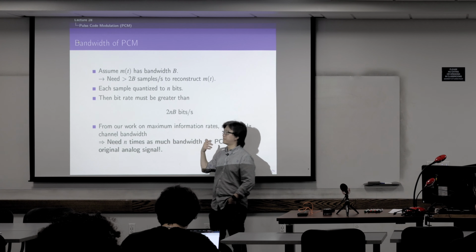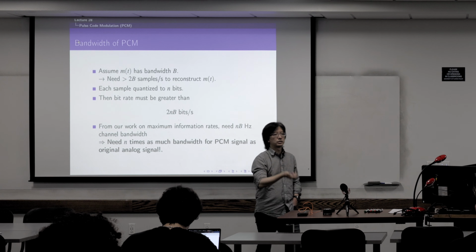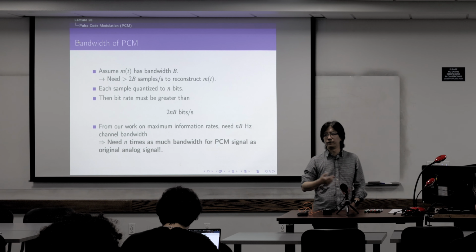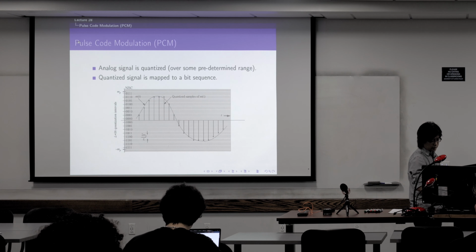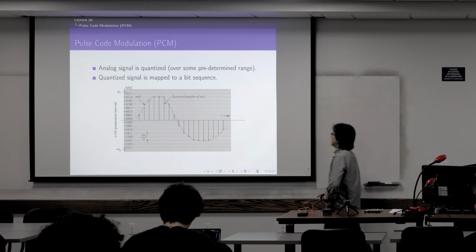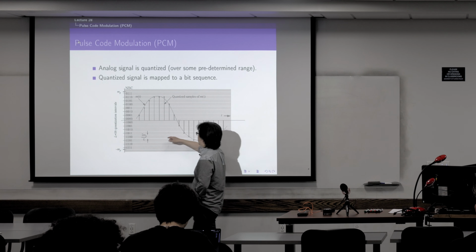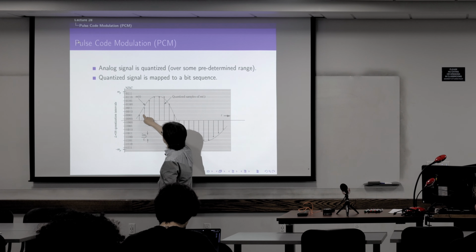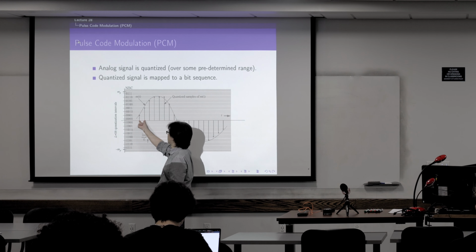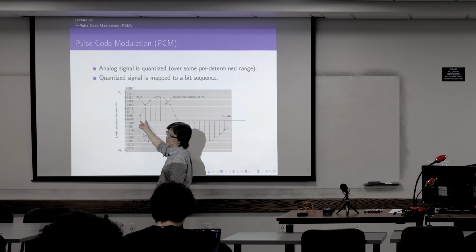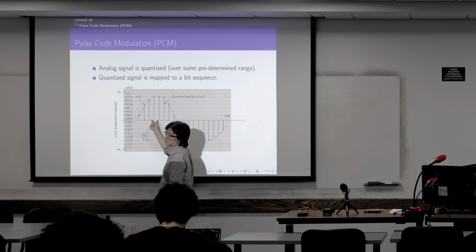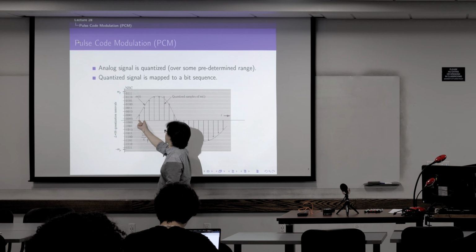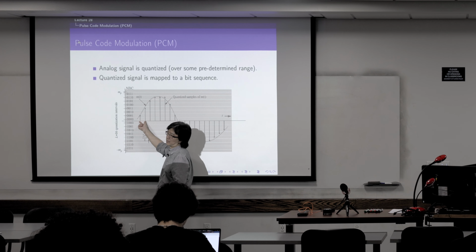So which is n times bigger than if we don't use a PCM, right? If we think about it again, intuitively it could mean that, basically, let's say we just transmit those levels directly using a rectangle pulse as wide as this. So there will be a bunch of these rectangle pulses this big, and then the bandwidth is, more or less, 1 over this width.